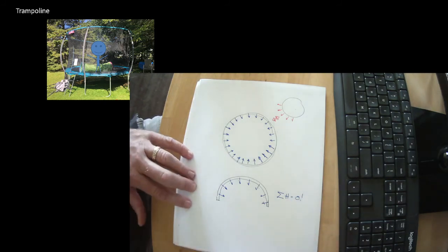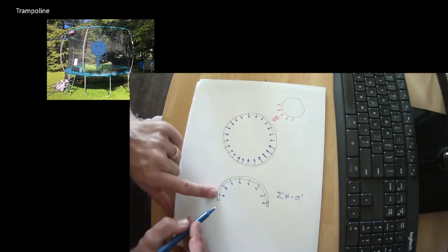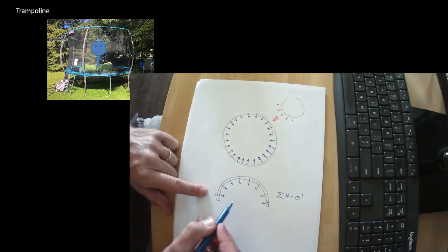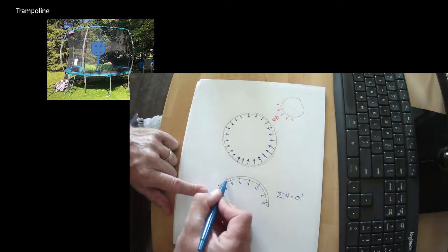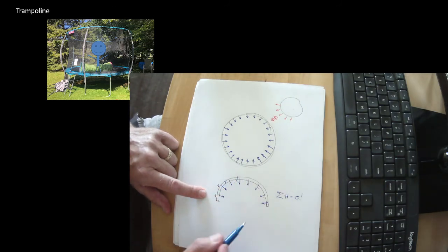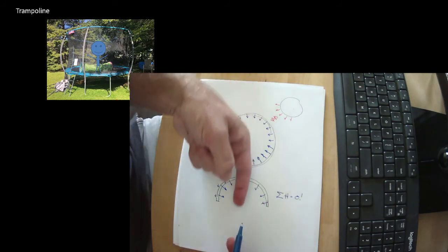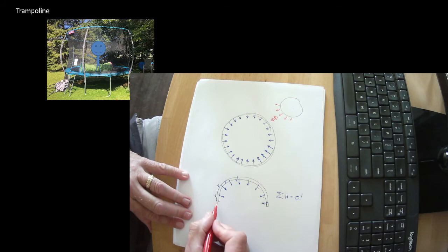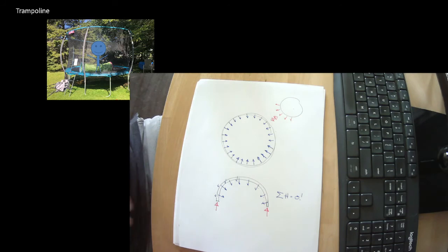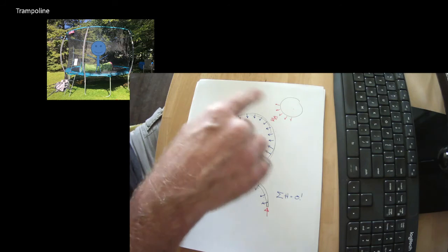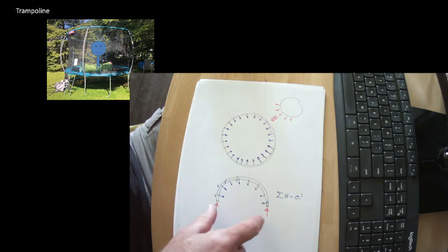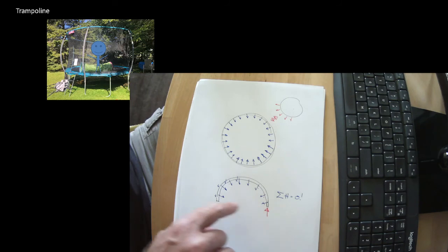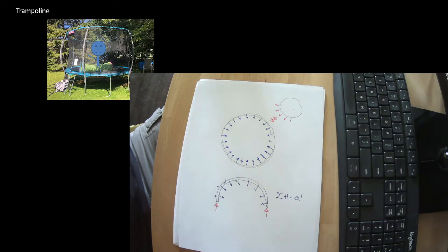So what's left? Well, we can see that this one has a small vertical component. This one has a slightly larger. This one has a slightly larger. So each one of these contributes a vertical load. And so we're held in equilibrium like this. So here we've done a section, a portion of it, held in equilibrium by vertical loads that are tangent to our ring. And that is a diagram that's in equilibrium.